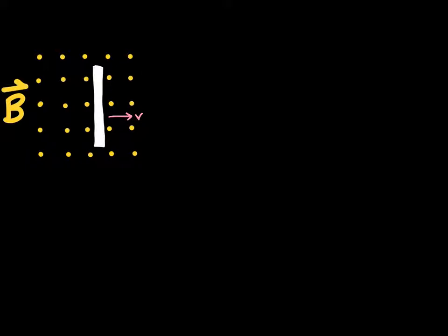And that means that I can use this right-hand rule to talk about what's the magnetic force on a positively charged particle and then flip it for the electrons because we're concerned about current flow. So this will require some contortion. The only downside of the easy draw of the arrows is that it causes us to twist around. So the magnetic field, you want to point the tip of your middle finger at yourself as opposed to its long side. Okay? So magnetic field pointing at your nose.